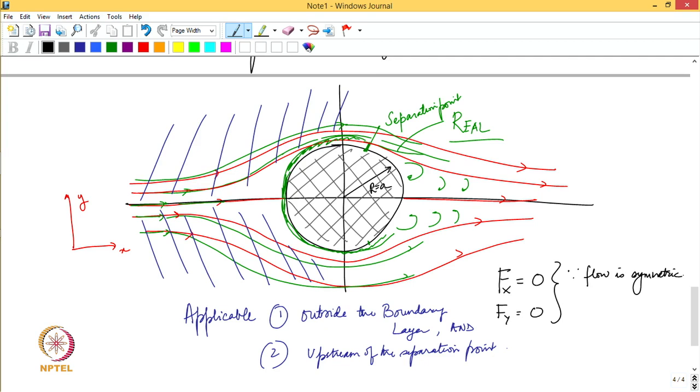The pressure field basically used to come from outside. The pressure comes from outside and is brought in at the edge of the boundary layer, so you get the pressure in the direction normal to the surface and then you impose it within the boundary layer. That is how the earlier CFD solvers used to work.